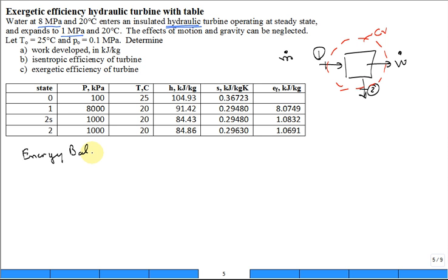What do we find? We find that the mass flow rate times enthalpy 1 minus enthalpy 2 is equal to W dot. Do you agree? Thumbs up? Couple steps. You should go slowly as you study, but I only have a limited amount of space, and I need to go a little faster, okay? But you need to make sure that you agree. Start with the most general equation, conservation of energy, and manipulate each term. Now, it's an insulated turbine, so we know Q dot is equal to 0, etc. Or you have to say, I'm going to make this assumption.